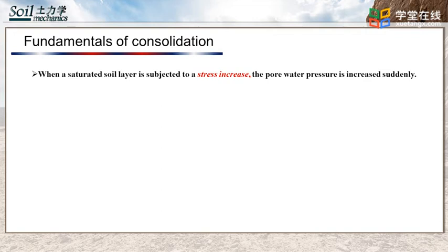Then, let's discuss fundamentals of consolidation. When a saturated soil layer is subjected to a stress increase, the pore water pressure is increased suddenly.